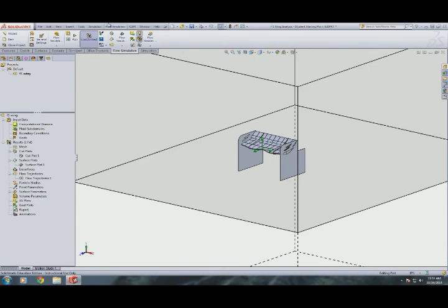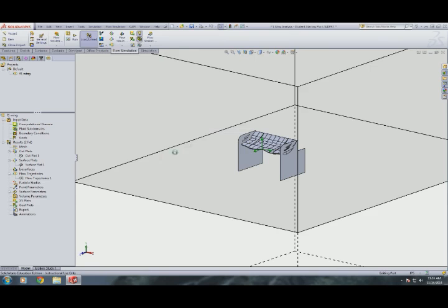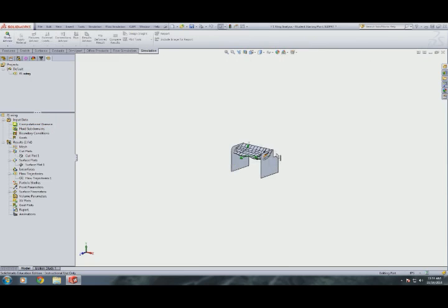So before we leave Flow Simulation, let's go to FlowSim, Tools, Export Results to Sim. You'll do some things and pretty much finish up there. So let's go to Simulation now and set all this stuff up after turning off Computational Domain, not edit, hide. So that way it gets out of our way.